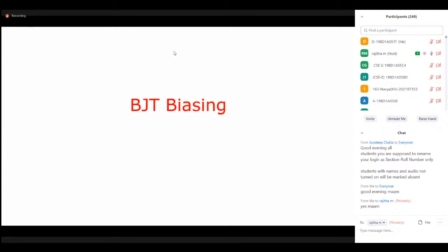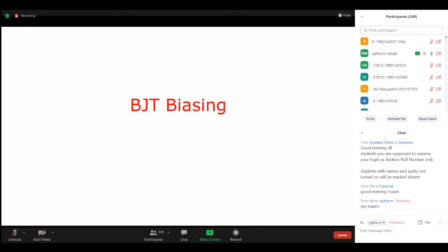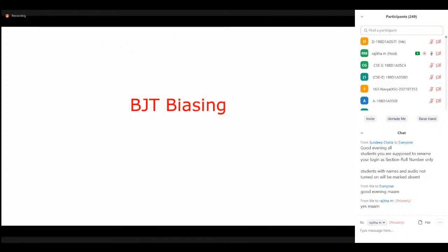Now how can this transistor act like an amplifier? Only under the active region, or the linear region. What we mean by linear region is that the current varies linearly with the applied voltages. The portion where the current varies linearly with respect to the applied voltages, with a factor of beta, is known as the linear region or the active region. Hence, under the active region, your transistor acts like an amplifier.